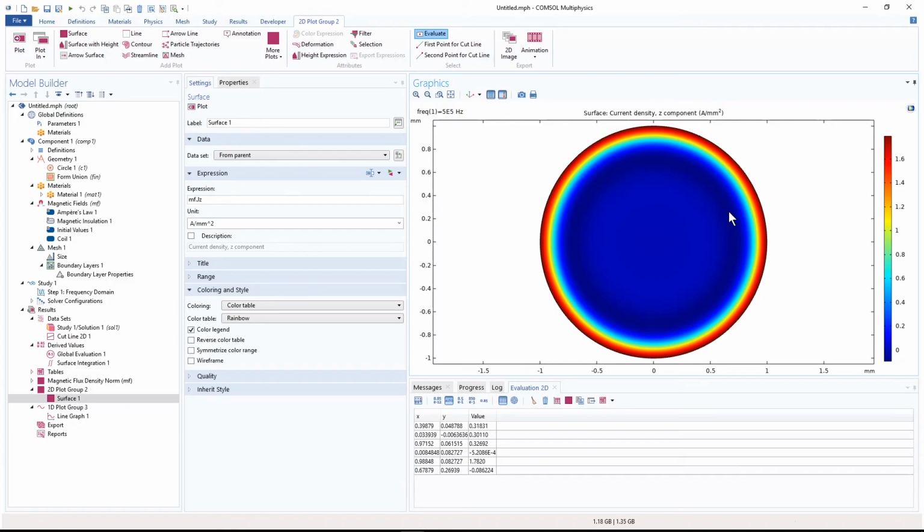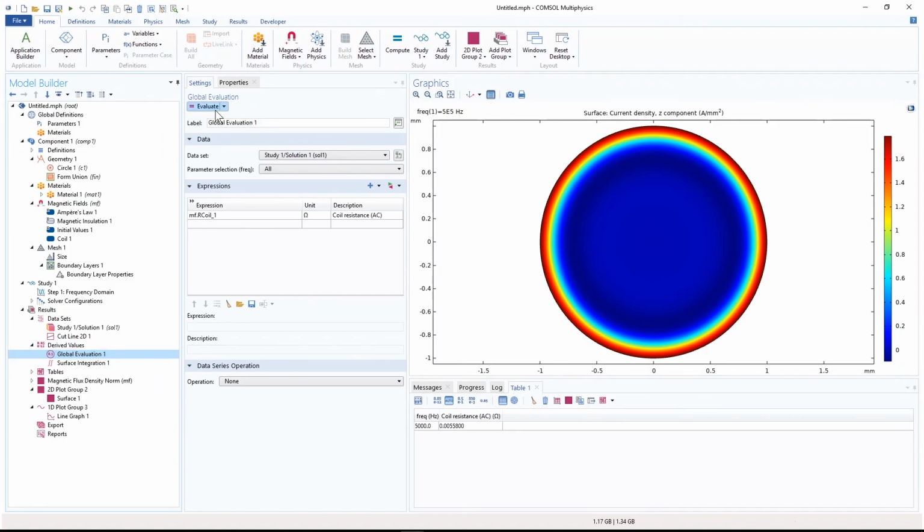Imagine if the total current of the conductor is coming toward us. At the edge, of course, the majority of current will concentrate coming to us, but just a little bit after that, in this region, the current is flowing backward. Or at least it has a phase shift, such that it creates a negative direction. It's very unintuitive, and it's difficult to explain by a simple explanation. But if we solve Maxwell's equations, we will see in the next video that all of these things can be predicted, and we will obtain the actual equations for how this kind of distribution will look for this simple case.